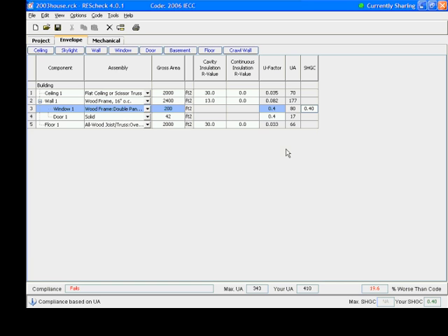We're not meeting it there, so we can't even start trading off to that hard limit. And there is a hard limit to trade off up to in this climate zone. We can't even do that yet, because we're not trading anything off, right? So down here at the floor, this is the only component that's actually meeting the minimum for this climate zone, which is an R30.